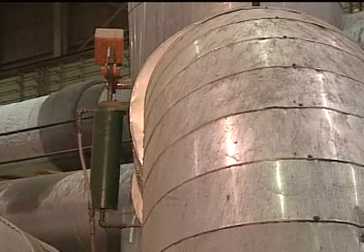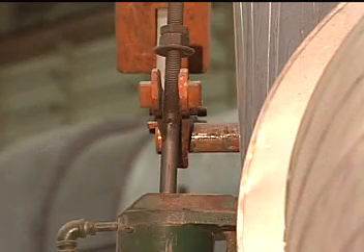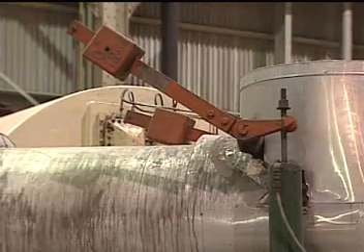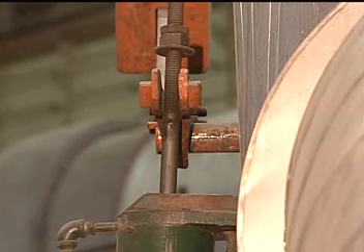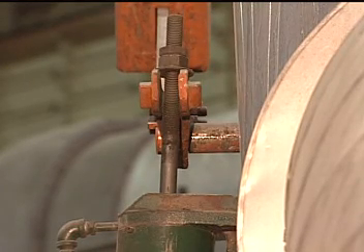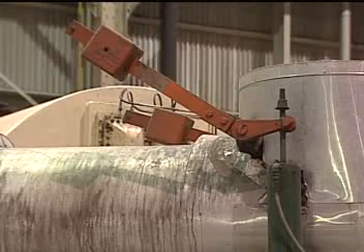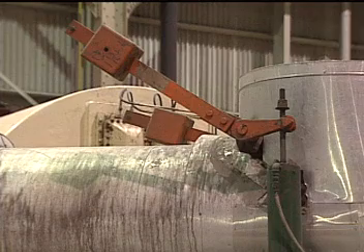Another important check is to inspect the non-return valves in the extraction steam system. You can visually check the position of a non-return valve. During normal operation, the valve should be open. However, a non-return valve's disc should be able to move freely so the valve can close when necessary. In some cases, you may be able to push up on the valve's operating arm to make sure that the disc is free to move.